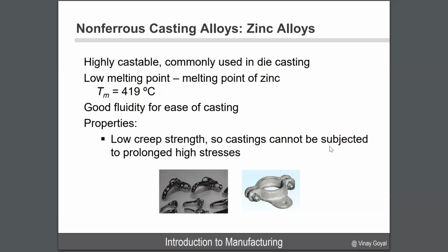What we found was that the joints on how these cables were secured were inserted into these joints using zinc casting. And because of Hurricane Maria and subsequent creep environments of sustained load conditions over a long period of time, it was found that the zinc started to creep over time. So slowly, the zinc was getting pulled from the socket until it gave out and it broke apart.